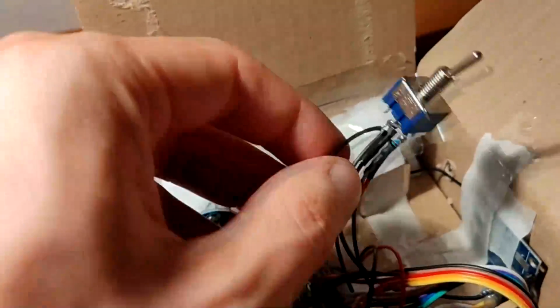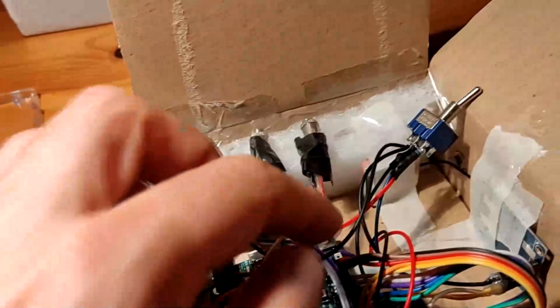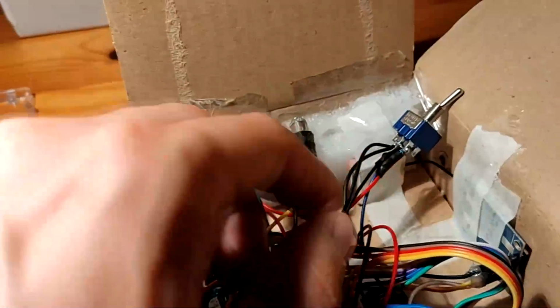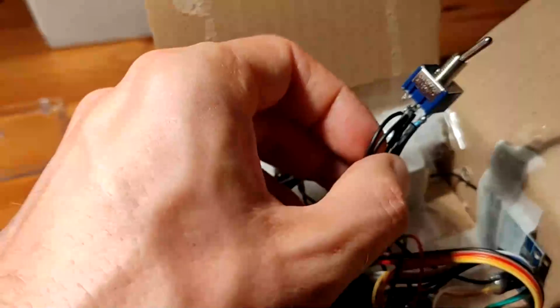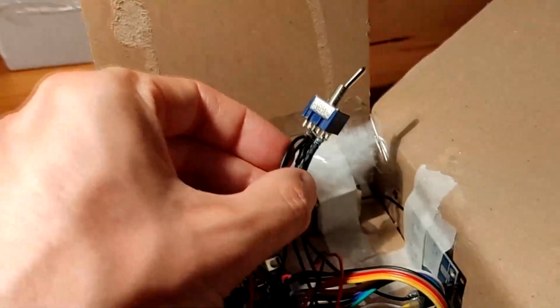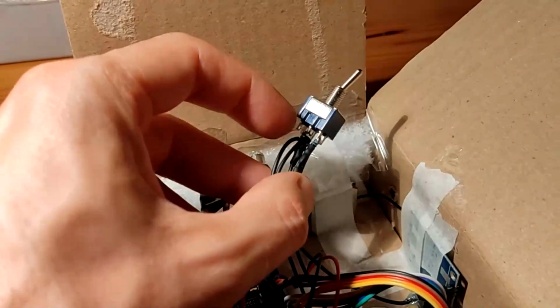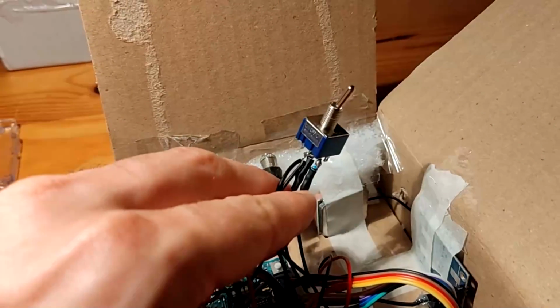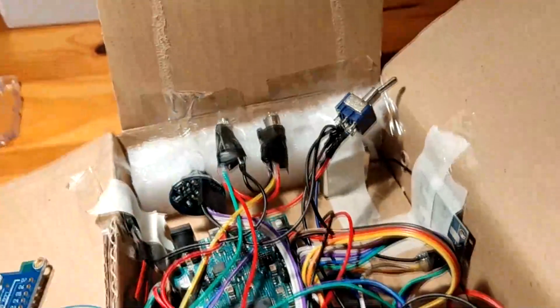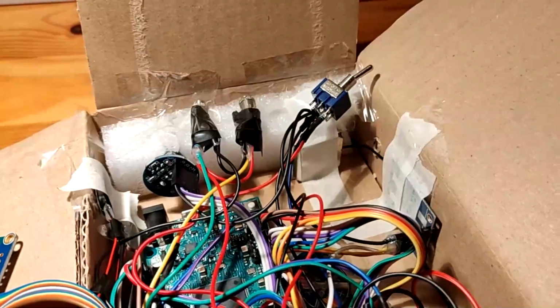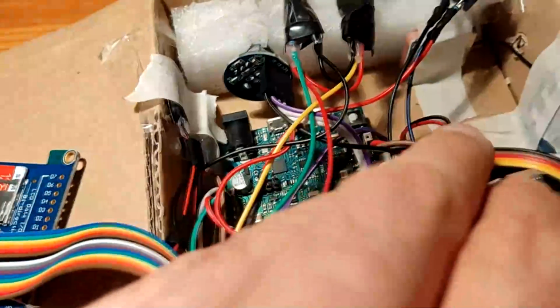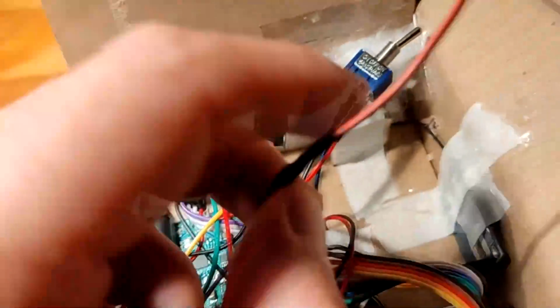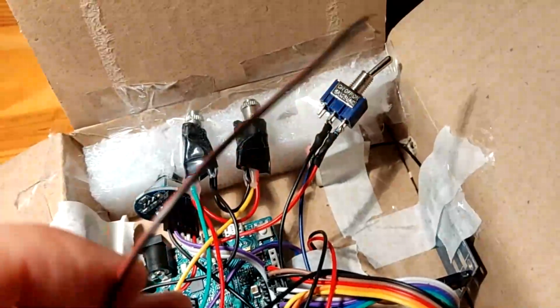So I stopped now to explain something. I've soldered the black wires, the grounds of the rotary encoder and the GPS module, to the ground of the switch, but I've soldered it above the resistor, and the wire below was going to my ground path, so I had a resistance in the ground, which is not good. So I removed the solder and soldered the two grounds of the rotary encoder and the GPS together to a big wire, because we need a strong wire for the ground of the GPS module.